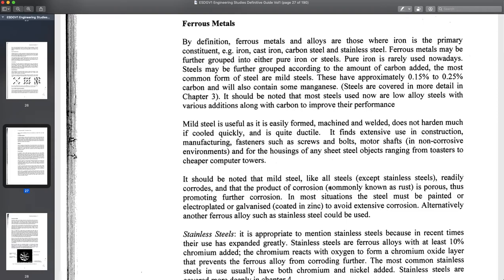Mild steel is mostly iron, because it's a ferrous metal, ferrum being the Latin word for iron, and in French it's fer, like chemin de fer, the road of iron, the railroad. It's mostly made out of iron, but it has a tiny amount of carbon. Do you know how much carbon it has? Less than 1%. How much less? 1/3 of a percent. If you took a percent and divided it into a third, that's how much. Another way of saying that is 0.3% carbon.